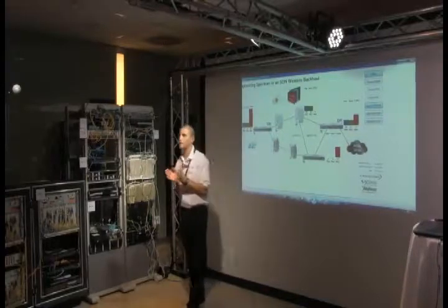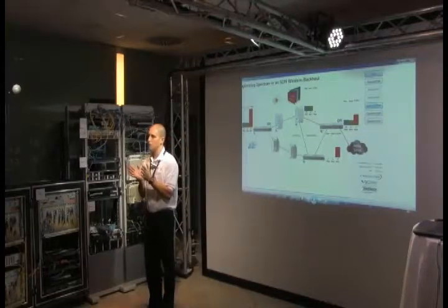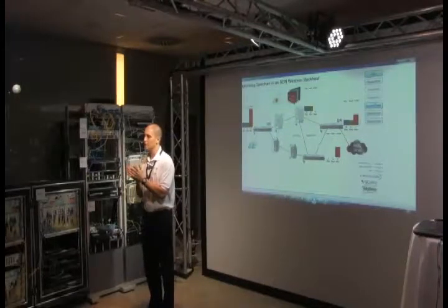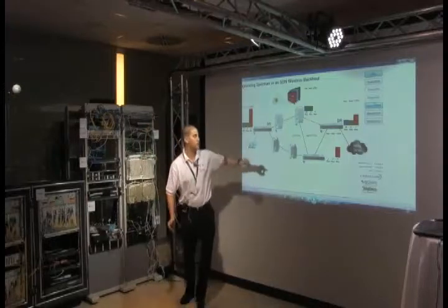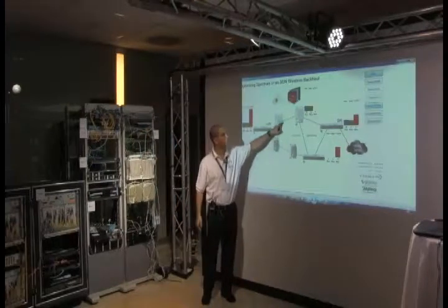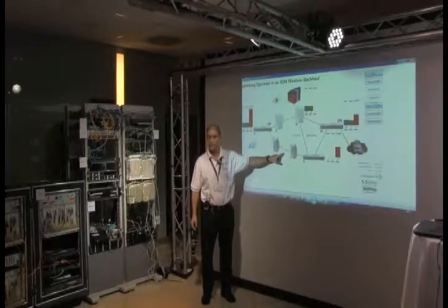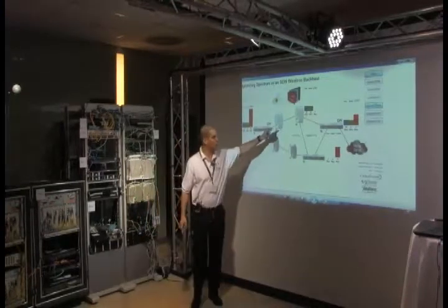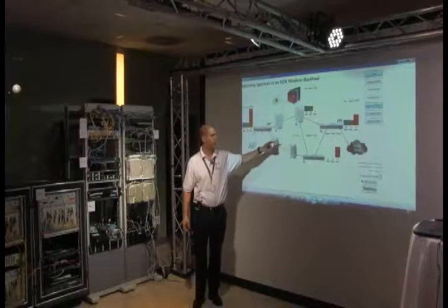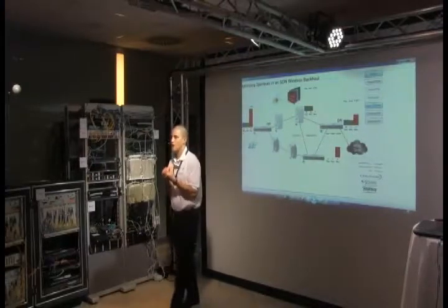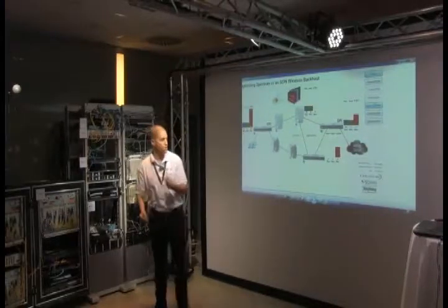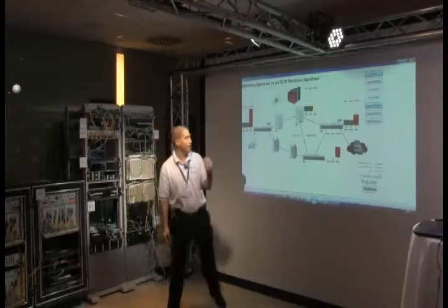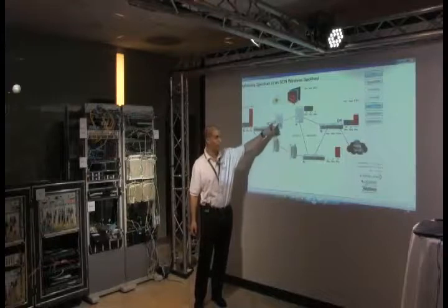Now, in today's planning condition, when you have 2 microwave links with an angle less than 90 degrees, you're not able to use the same frequency. Okay, so I have to use a blue frequency and a red frequency. Now, the reason I use 2 different frequencies isn't because the links are actually disturbing each other. It's because there is a certain chance that under specific weather conditions, they will. And because I'm planning for the worst case, okay, I must use different frequencies for both links.